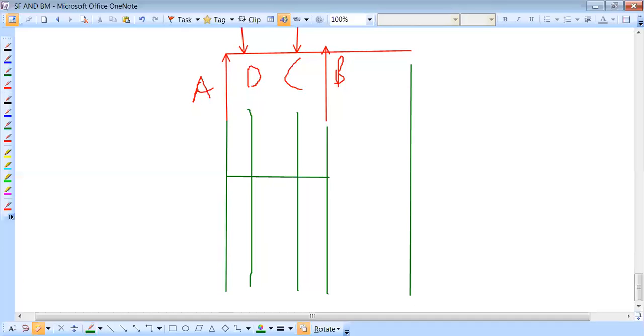So it is this line, and again draw here. At the free end SF is equal to 0, no force between this, so also 0. But here at B, the value is positive, so we can take positive here. You can take a straight line from here to here. What is the value of this point? We already found positive 1.75.